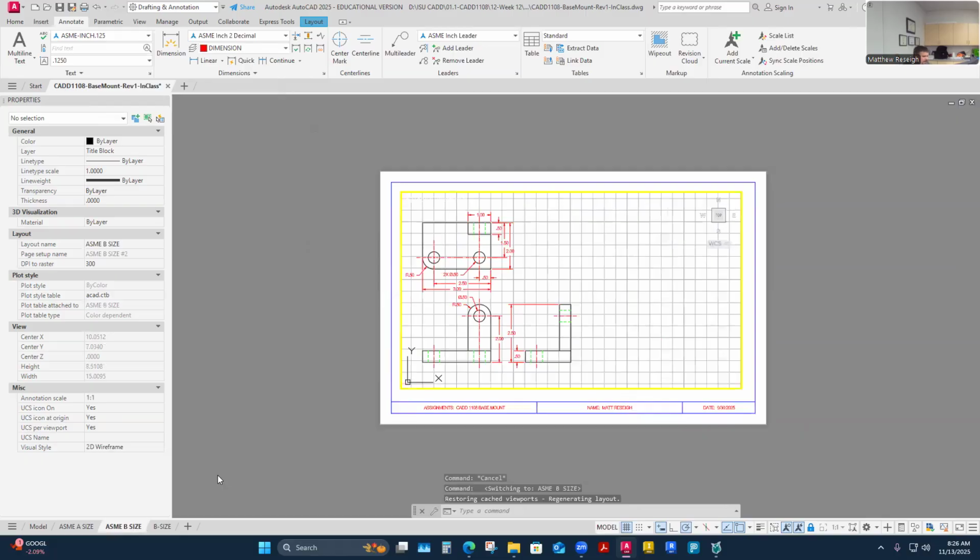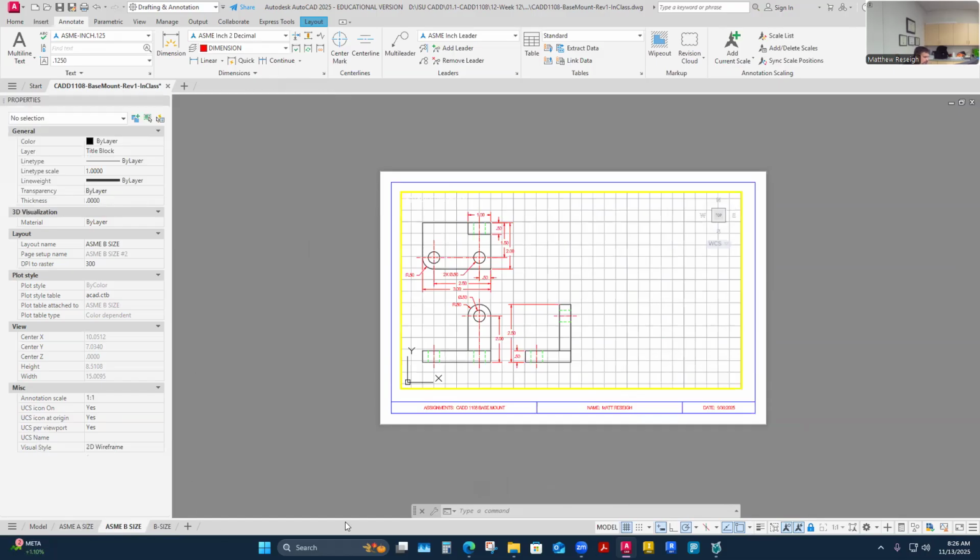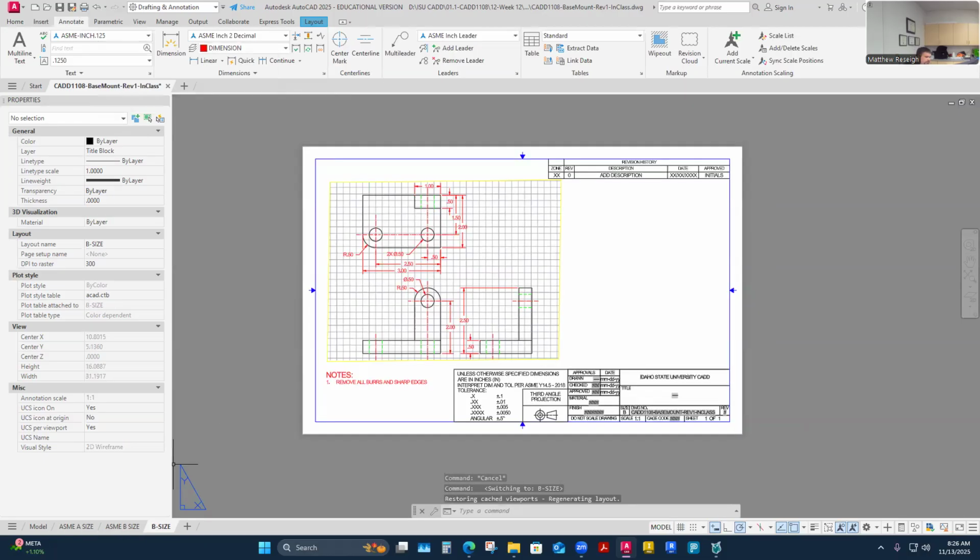And then I just want to show you right off the bat the batch plot idea here. And then I'll get into actually drawing. So a batch plot is when I've got my one drawing here. It has one drawing number. It might have a bunch of sheets. It might be 20 sheets. Ours now has 3 sheets, even though I really only need one. I'm going to treat this as if I had 3 different sheets now, and show you how to put that in as one PDF. I think it's just helpful.